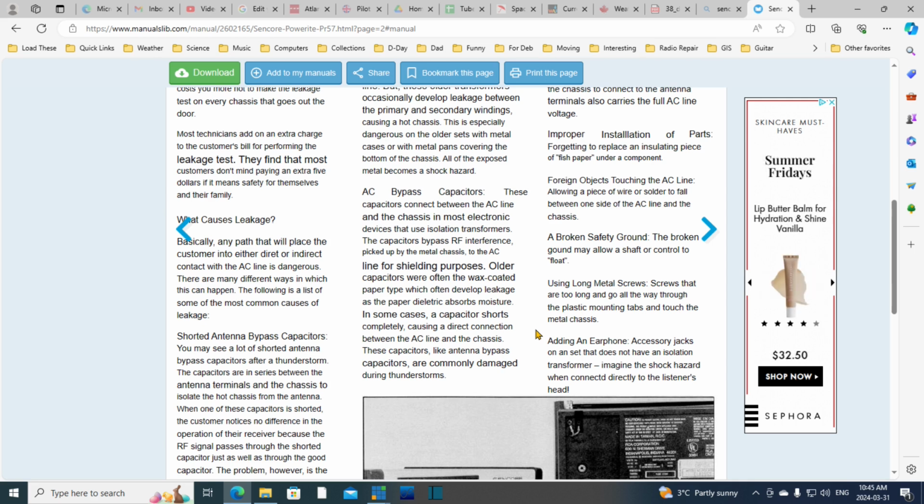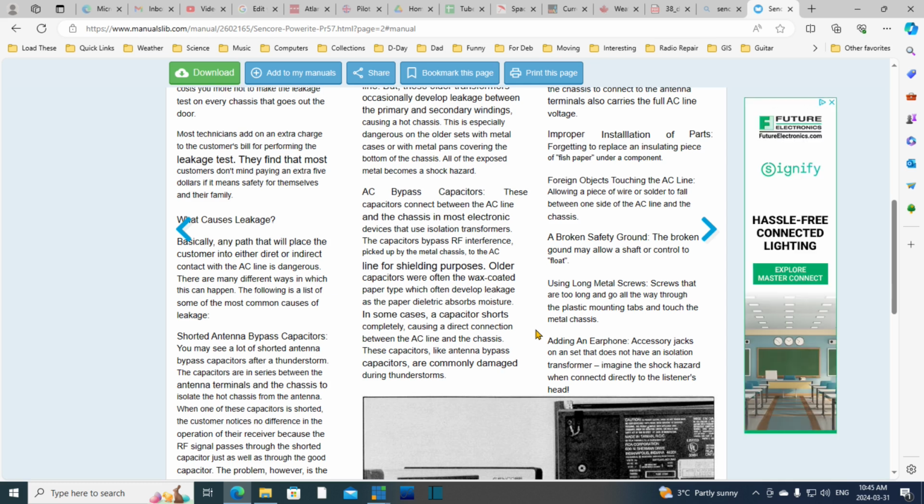What you could do is extend wires under the ground around the outside of the fence. Buried ground wires, maybe going 2-3 meters, far enough away that you can stand there and can't touch the fence anymore. And if you did, it didn't matter, because the ground is now being lifted up also. The ground you're standing on is being lifted up to 8,000 volts or whatever. You won't get a shock.